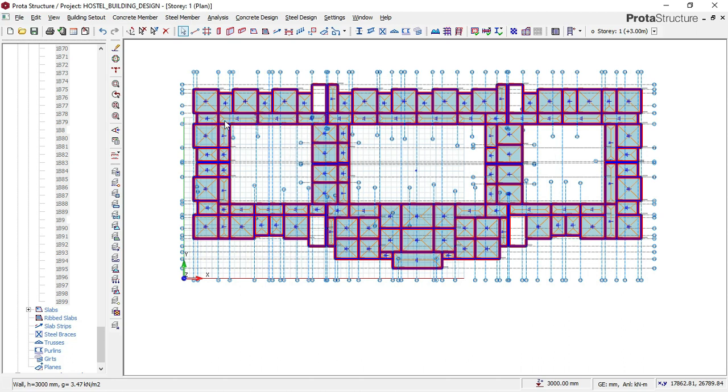So we are going to remove wall load on this area because there is no wall on this courtyard perimeter beams, and also on this one we will take off all the wall load on this area, and also here we take off the wall load on this area too. That is the only place we are going to take off the wall loads: this area of the courtyard, the perimeter beam within this courtyard, and also this area too.